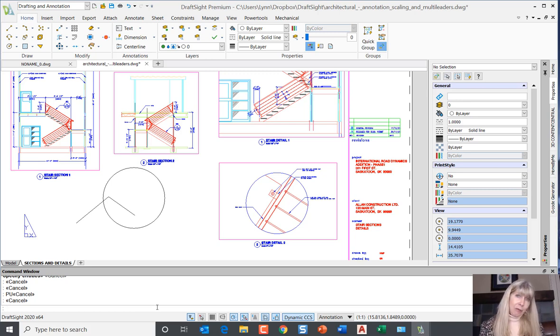All right, what else have I got for you? You'll see, of course, we have model space and paper space, the layout tabs, once again, very similar. And across the bottom of the screen, we have the status bar. Not nearly as congested as the AutoCAD status bar, thank goodness. But what have I got down here? We have snap and grid and ortho and polar, and we have E-snap, that's the same as object snap, so you can set those up.